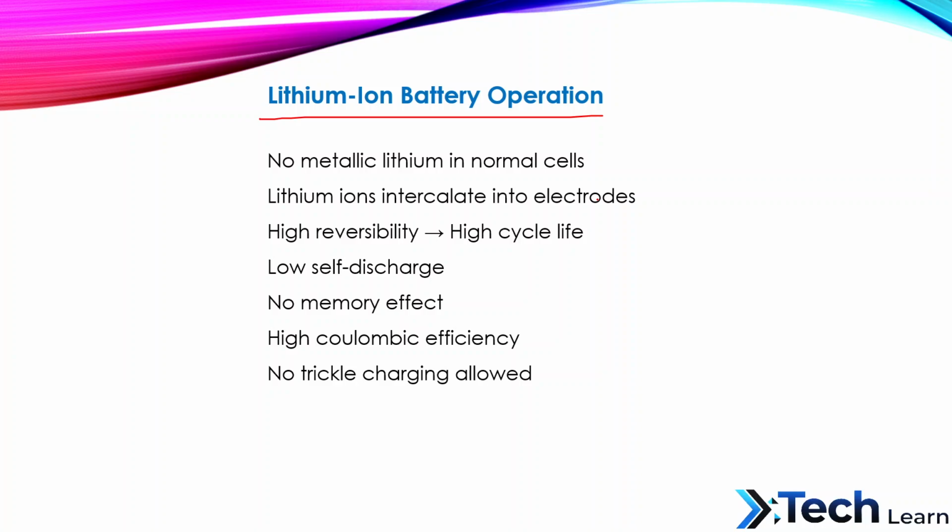They have very low self-discharge and no memory effect, giving users flexibility in charging. However, unlike nickel cadmium or nickel metal hydride batteries, lithium-ion batteries cannot be trickle charged. Even a small overcharge current can damage the cell and create unsafe conditions.